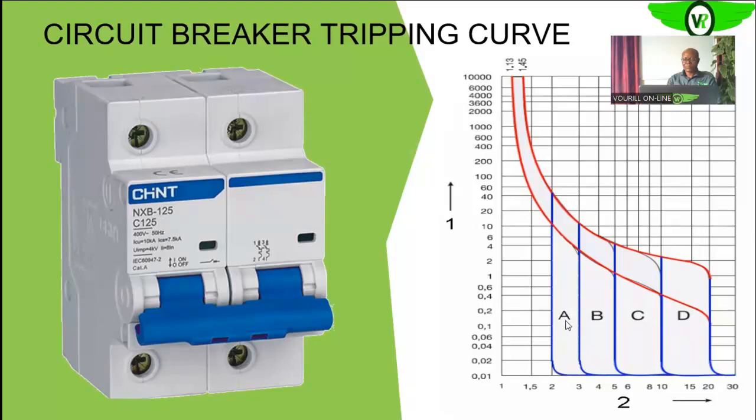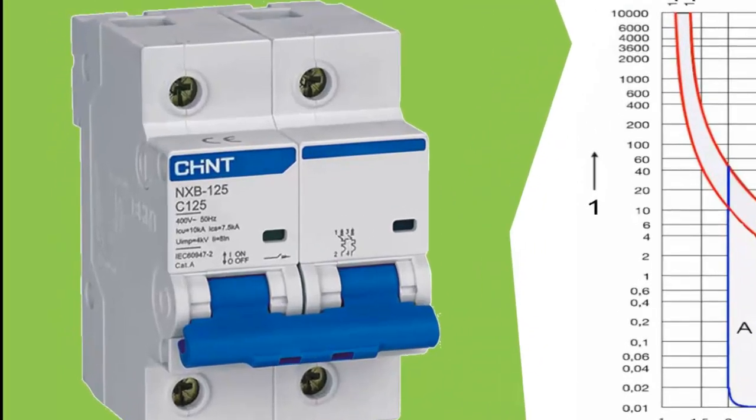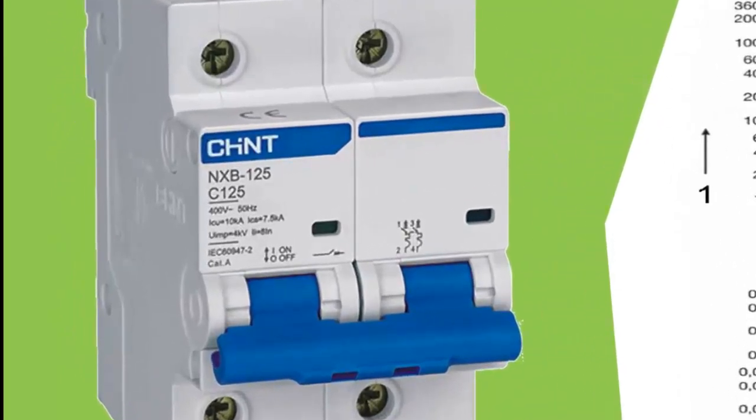If the operation of the breaker is guided by the A curve, it will trip instantaneously between 2 times and 3 times the rated current of your circuit breaker. B, between 3 times and 5 times. C, between 5 times and 10 times. And of course D, between 10 and 20 times the rated current of your circuit breaker.